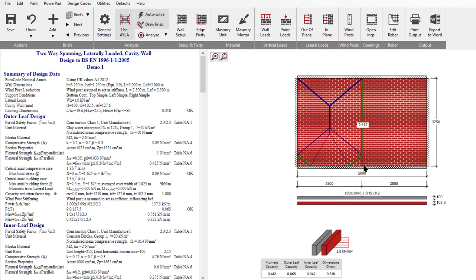We're looking at this wind post enhancing the overall strength, because we're not designing the wind post as a separate component. We're designing it as glued onto the wall in whatever fashion and enhancing it. So in this case, the post is so strong that the flexing is flexing across in this direction. So it's going from here, here, and the big yield line down there. So those are the two different ways that we can handle the wind post.